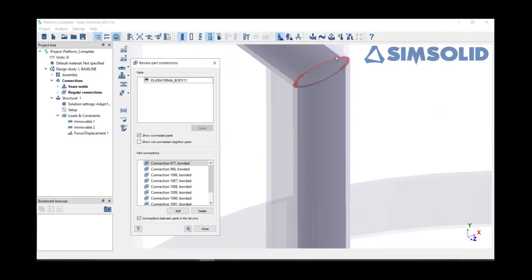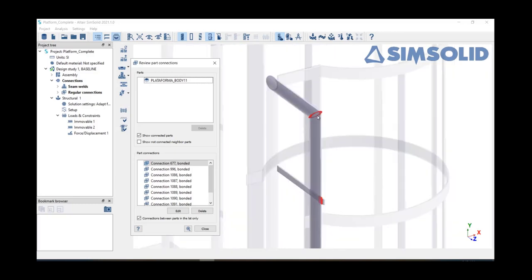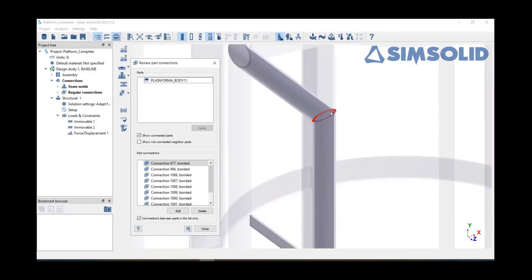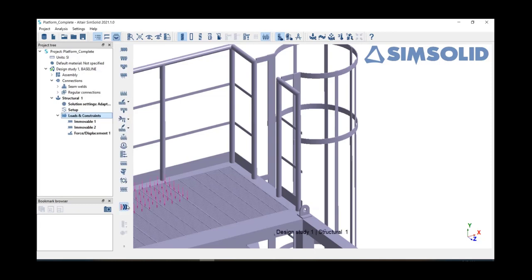you see that there are full contacts made. The issue is more that they're separated out into different contacts. So it's not that we're going to have this hinging or not fully connected. It's just if we want to go in and do some kind of contact pressure analysis, we're going to have to consider multiple contact faces. They're just spread out over different connections. This will take potentially a couple seconds longer to run just because we have those higher resolution connections that we've made in the model.